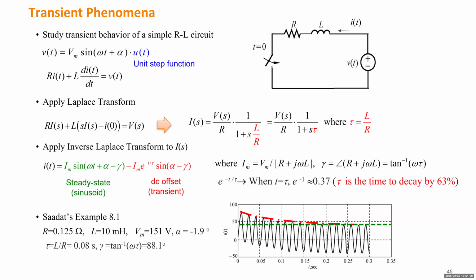Okay, and next, we have so many parameters from the generator. We just need to select which parameters fall into which dynamic. If you have a very fast dynamic, it means the time constant is very small. Then we need to know which L and which R will cause this tau. Like for subtransient dynamic, let's say tau is 0.01 or less than 0.1, we need to figure out which L and which R will create this tau.